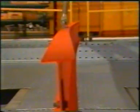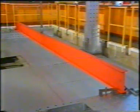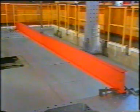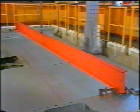The direction of the lateral movement is determined by the initial imperfections present in the unloaded beam. When the beam is unloaded, full recovery occurs, with the beam returning to its original undistorted shape. No permanent damage has been done to the beam, which demonstrates that the failure is elastic in nature and is due to instability.